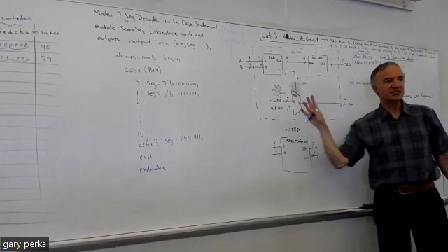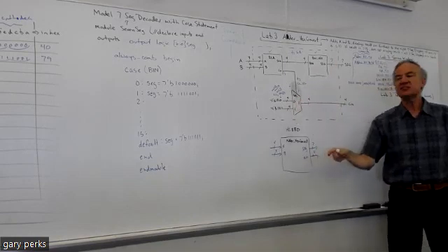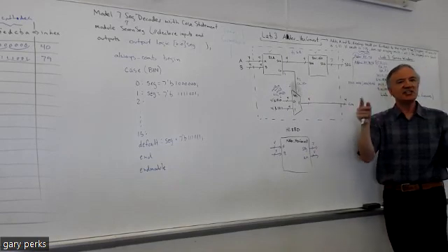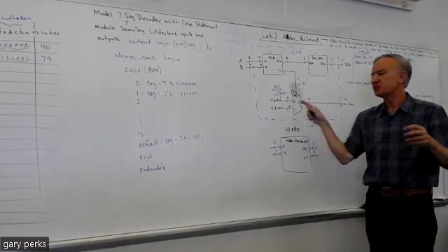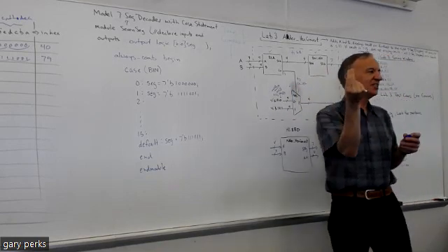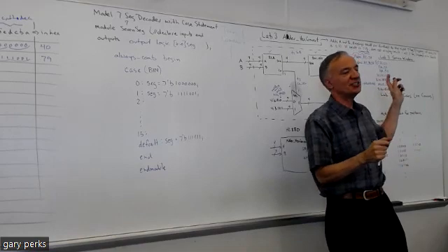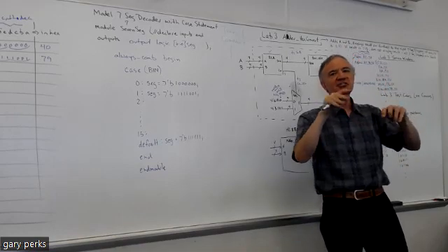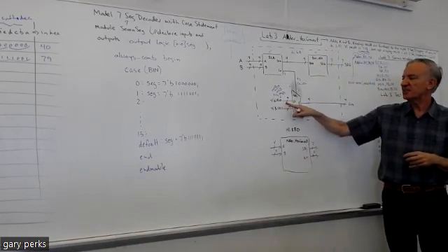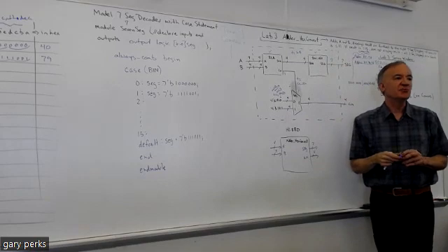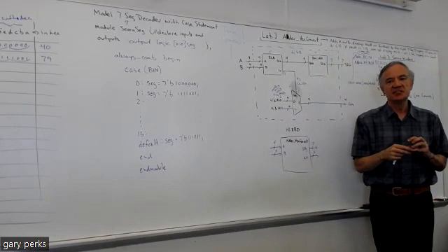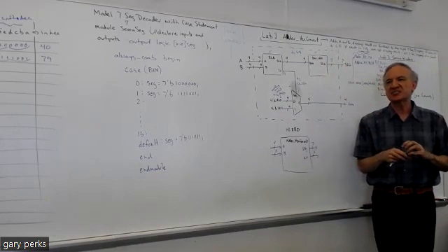If you make the connections to data in the structural model, you can keep your mux general. It's like when you designed your mux, you just made output equal whatever you call this input. You didn't connect it to specific data in your design source. That's the best way to do it: make your lower level modules general, and then anything specific, like a specific amount of data that you want to connect to an input, you just do it in the top, where you make all your other connections. That's sort of like standard practice.